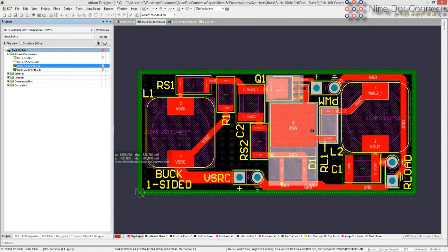You'll see that the node between them is right here. That node, the VSW node, is so small you can't really get it any smaller than that. You'll see that it does have some adjacency to other parts. You could conceivably rotate a few parts to keep it further away, but in general, you're getting about as close as you can.